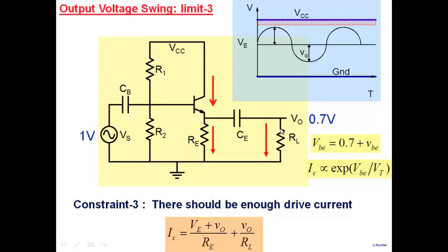So it's not likely to occur unless you make RL so small that, inside the transistor, there's a maximum current limit coming from power dissipation and many other limits. If you don't exceed that, then there's no issue with this circuit. My amplifier will be able to pump in more and more current as you reduce RL, until the point where you violate the internal current limit and power limit of your transistor. The problem doesn't come in the positive swing actually. The problem comes in the negative swing. So let's look at the negative swing part.